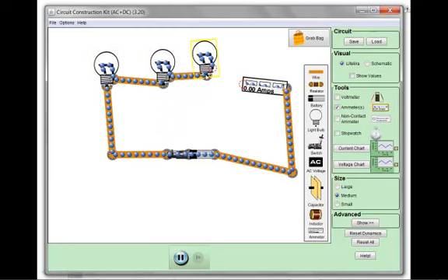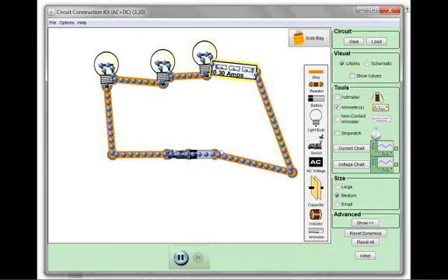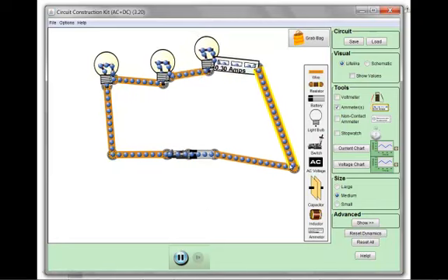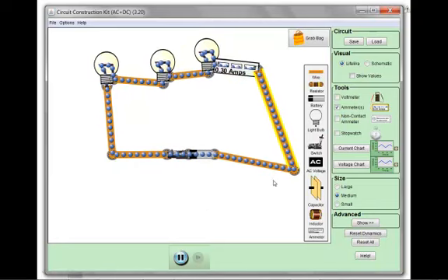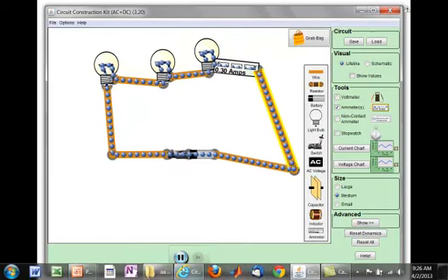Okay, so now it's connected to the bottom of that part of the light bulb. And before, I had my ammeter connected to the same point, the bottom point of the light bulb, so we were essentially bypassing the current through there. But now I'm going to connect it to the right place, and we're getting 0.3 amps like we're supposed to get. So that's how you measure the current in a circuit. You have to put the ammeter in series with the elements. Let's return to our show.